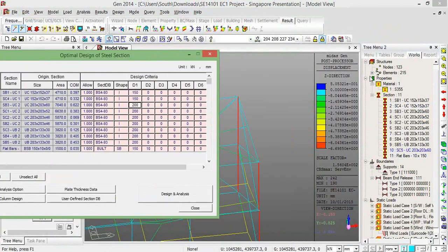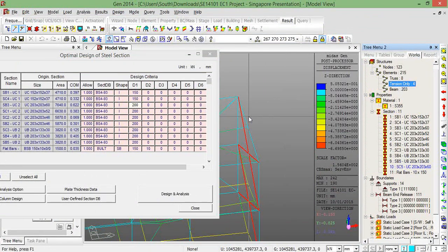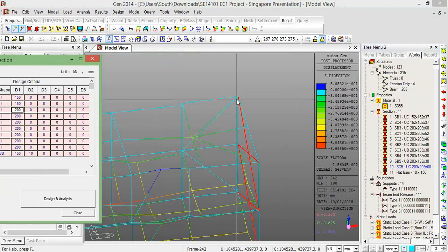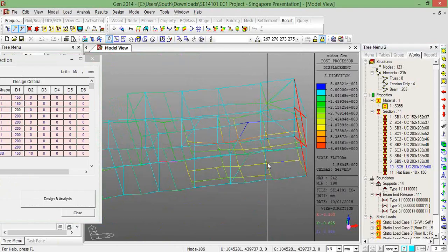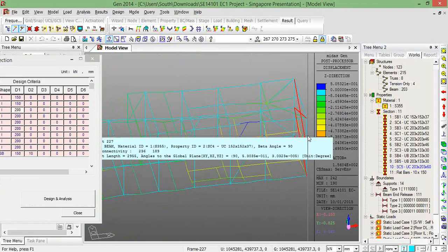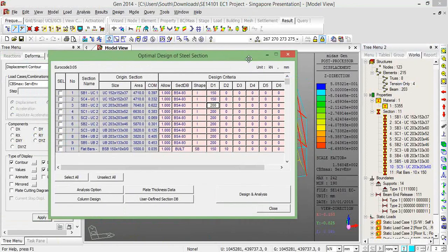These have been designed actually as tension-only members. So when in the design case, they're only ever working in tension. So if the wind blows in the Y direction, only those ones in tension would work and would be represented in the results. If the wind was blowing in the minus Y direction, the opposite would happen. But again, for the ease of the connection details and allowing edge distances for bolts, etc., this is why we chose this particular size of member.